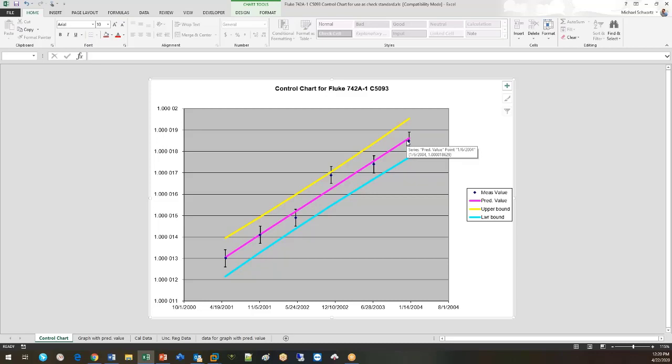It depends. The bound is based on the 6 data points you have, right? So you calculate the standard deviation, and you can set 2 sigma or 3 sigma of the values as your control limits. If you set control limits and you go over, then you have to investigate what's going on. 2 sigma, 3 sigma is up to you, depending on your confidence.